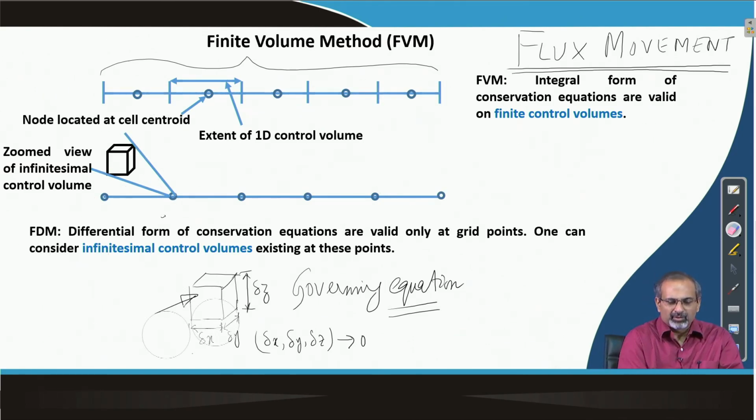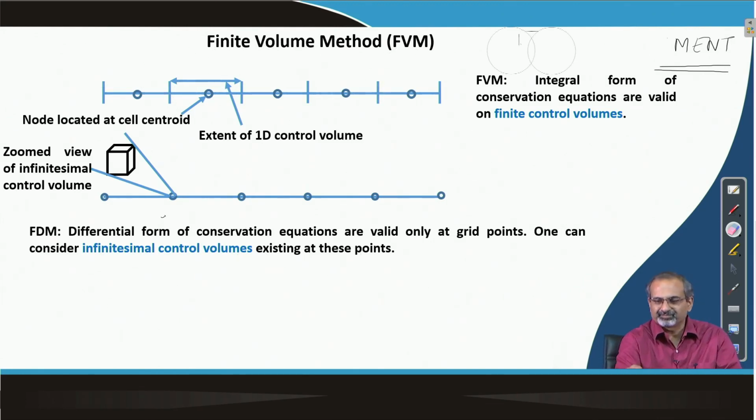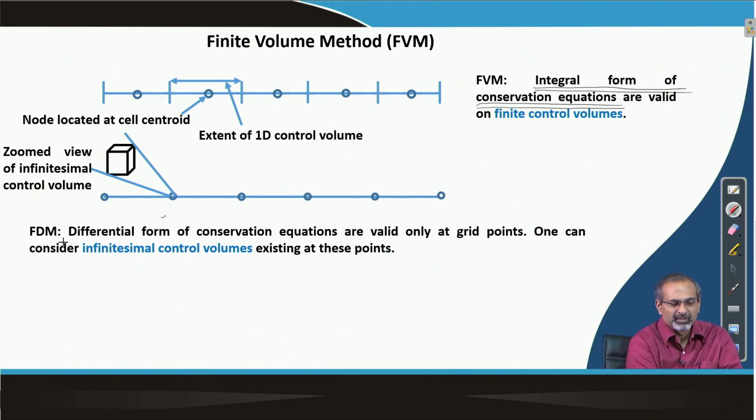We were talking about governing equations where we see derivatives. In the finite volume method, however, we deal with the integral form of the conservation equations. So, we do not use the differential form, but rather we use the integral form. So, keep in mind that the finite difference method was dealing with the differential form of conservation equations, while here we are going to deal with integral forms.